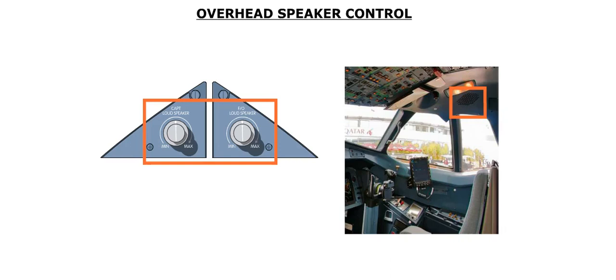There are 2 overhead speakers in the flight deck. The volume of these speakers is controlled by an associated loudspeaker volume control knob. The loudspeaker is muted during transmissions, to avoid any audio feedback through the system. It should be noted that the loudspeaker volume control knob does not change the volume of any aural alerts.